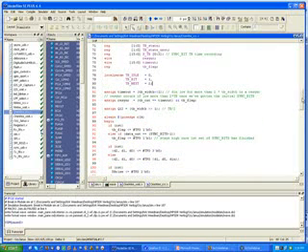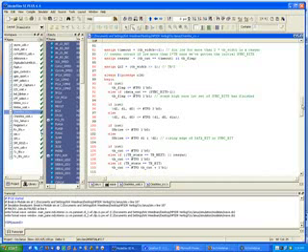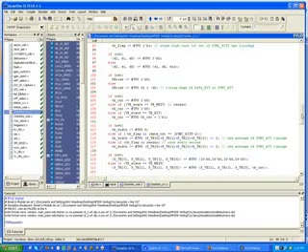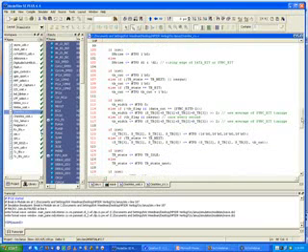So let's go down to the rest of the code here, and in this code you'll see that I have an always block that's running on the positive edge of clock. Okay, that's the only controlling event type statement in this always block, and because of the way I've written it, this is RTL code. This is a subset of the Verilog language that can be synthesized. We'll be talking more about that in the upcoming lectures.